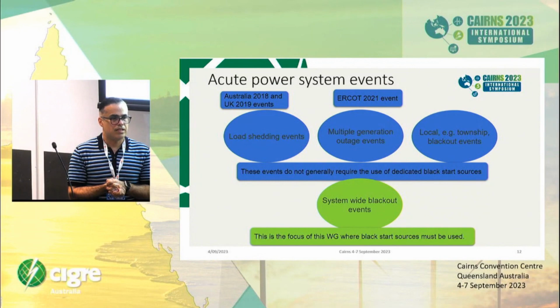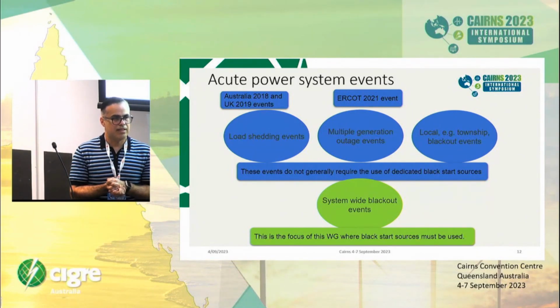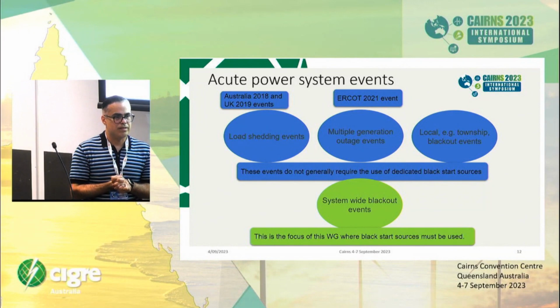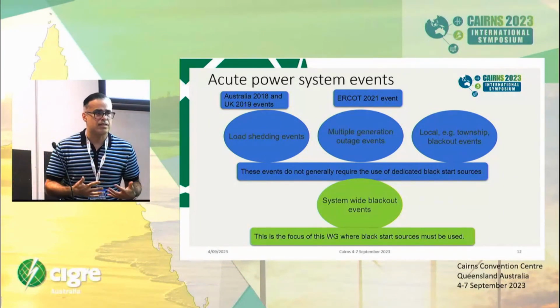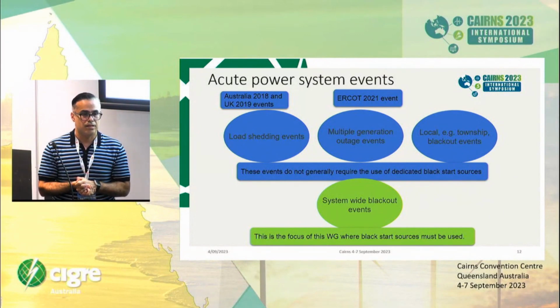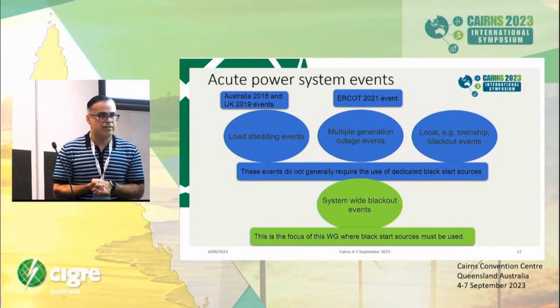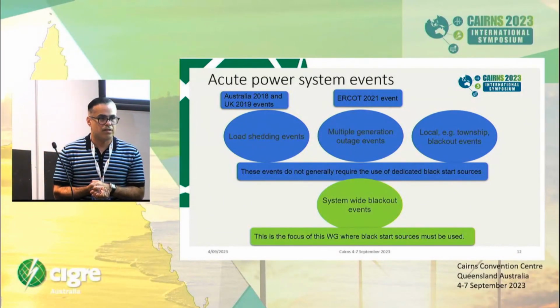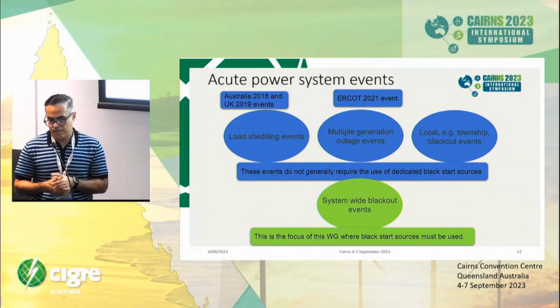These are load shedding events, for example, the one in ERCOT. You don't have fuel available, you can't do anything with it. The system is not black. The system is completely intact and healthy. They are very different things. What we are really talking about, and what system restoration is about, is that you have lost a part of your system that you have to restart, rather than not having fuel to allocate for loads. Likewise, in the UK event, yes, it's very unfortunate that loads were lost and trains stopped, but this is not a blackout, so no part of the network required restoration for that event.